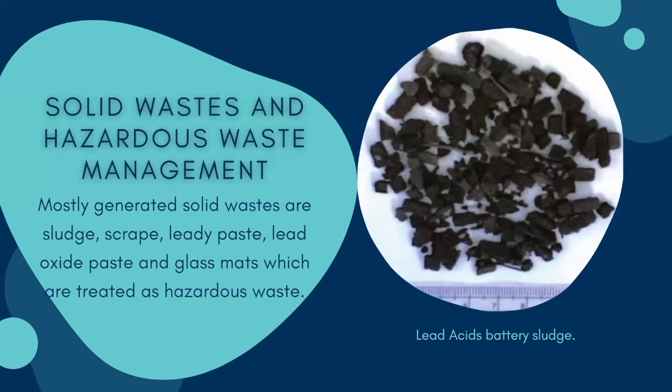This is a crucial one. Solid wastes and other hazardous waste management. Solid waste, also known as dry effluent, is practically in a dry state. Disposal basically depends upon the frequency of generation and production. Mostly generated solid wastes are sludge, scrap, leady paste, lead oxide paste, and glass mats, which are treated as hazardous waste.